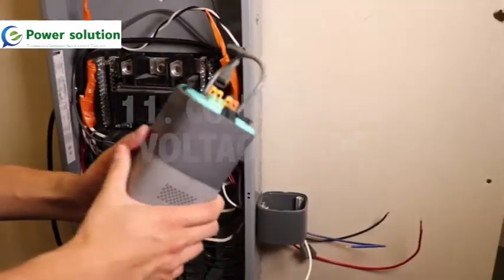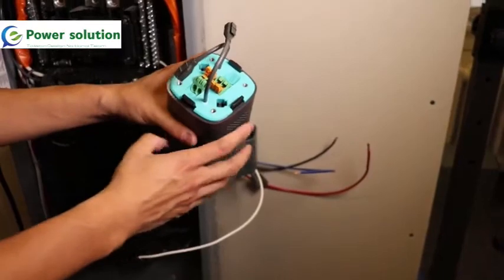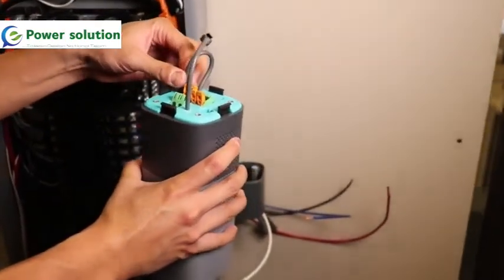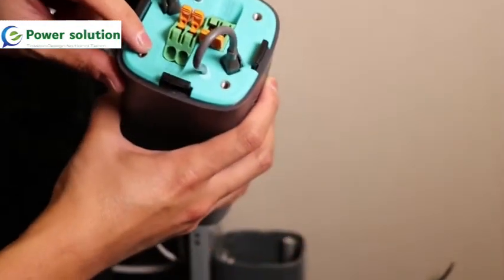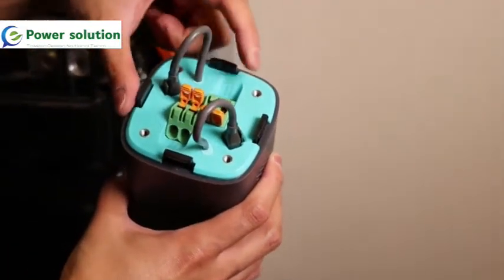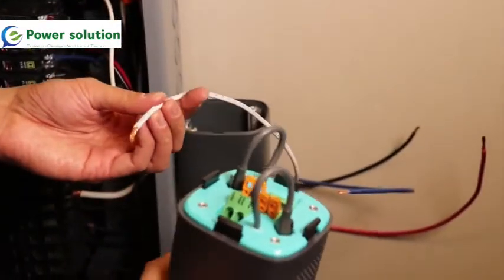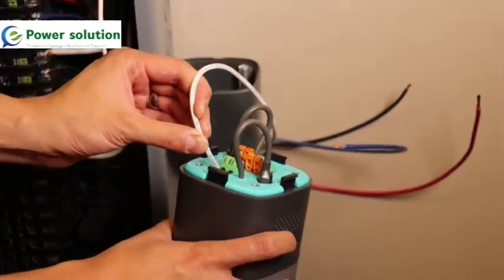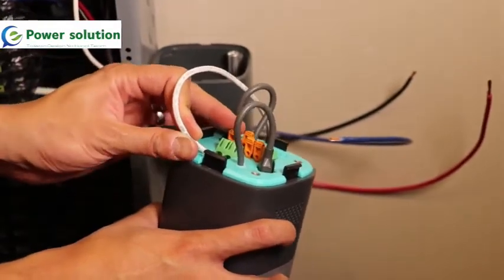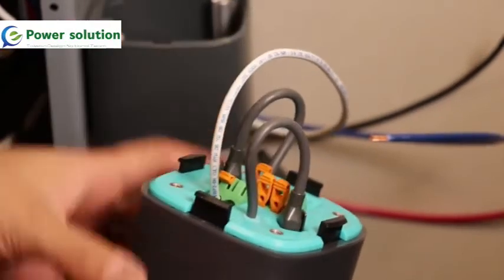So now we're going to connect our transmitter. First, we're going to connect the voltage cables. On the transmitter, there are 4 voltage taps, and you can see them labeled neutral, A, B, and C. We're going to take our voltage wires and connect them appropriately to each connection. So be sure that neutral goes into the neutral port. It's very important that we not expose the system to higher voltages than we would like for this port.